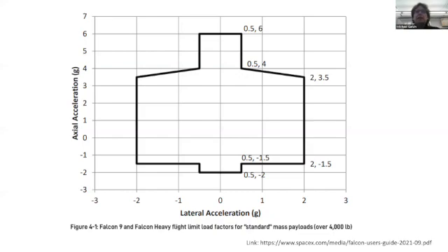But there are some semi-steady load factors resultant from that axial ascent and lateral turn that the rocket does. And certainly there are some load factors that you can assume most of the dynamic vibrational G loads fall under or are enveloped by. And that's what this plot will define.